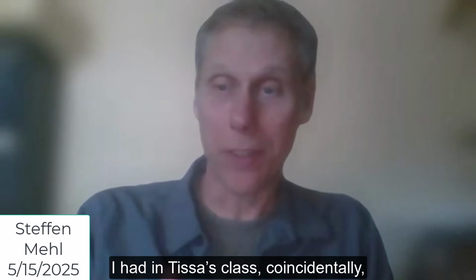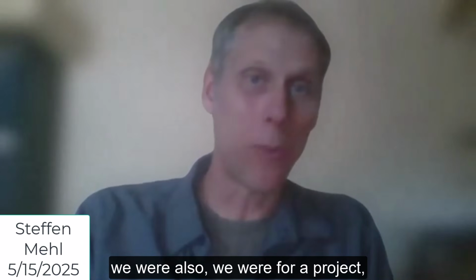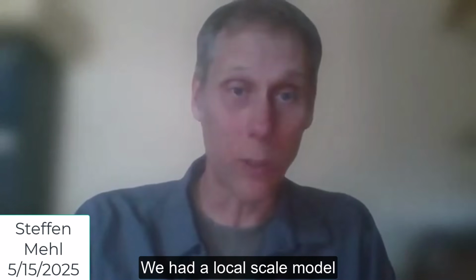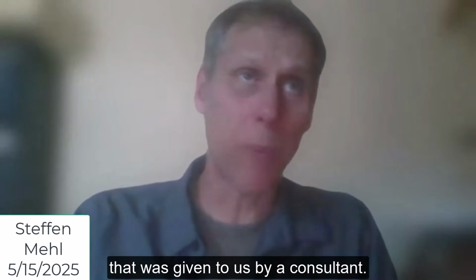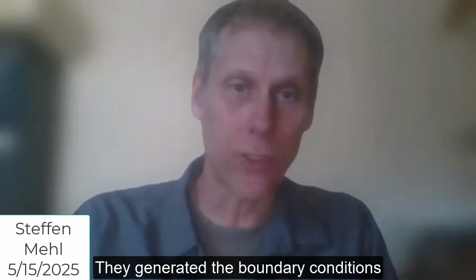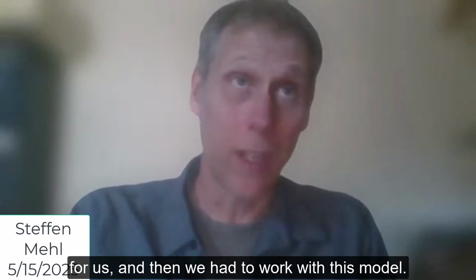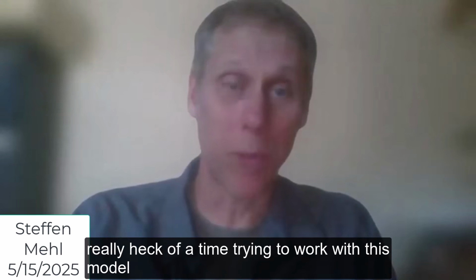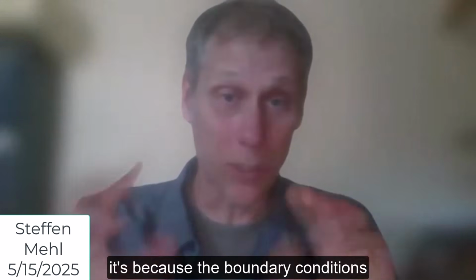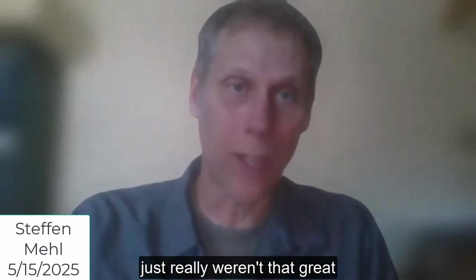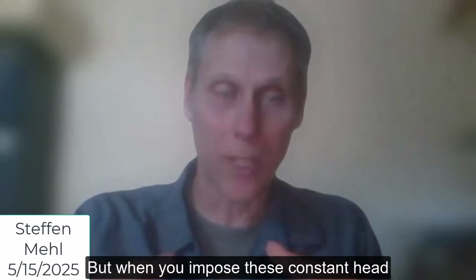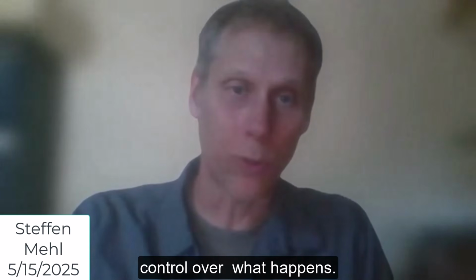I had, in Tisa's class, coincidentally, for our project, worked on some flow and transport model where we had a local scale model that was given to us by a consultant. They generated the boundary conditions for us, and then we had to work with this model. And our group in particular, we just had a really heck of a time trying to work with this model, and we realized later on it's because the boundary conditions just really weren't that great that were given to us. But when you impose these constant head boundary conditions, they just have so much control over what happens.